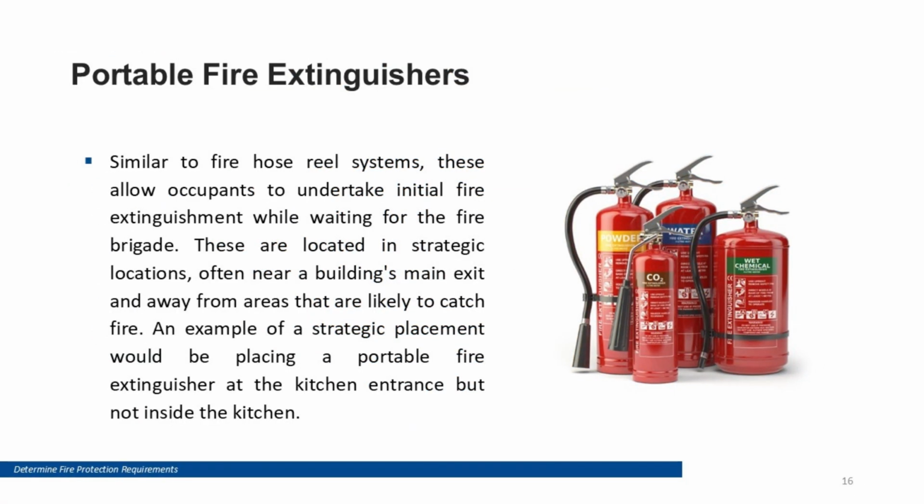Portable fire extinguishers. Extinguishers support early response, but selection must match the likely fire class. Placement also matters, usually near exits and away from the most dangerous ignition point, so occupants can access them safely during an evacuation.